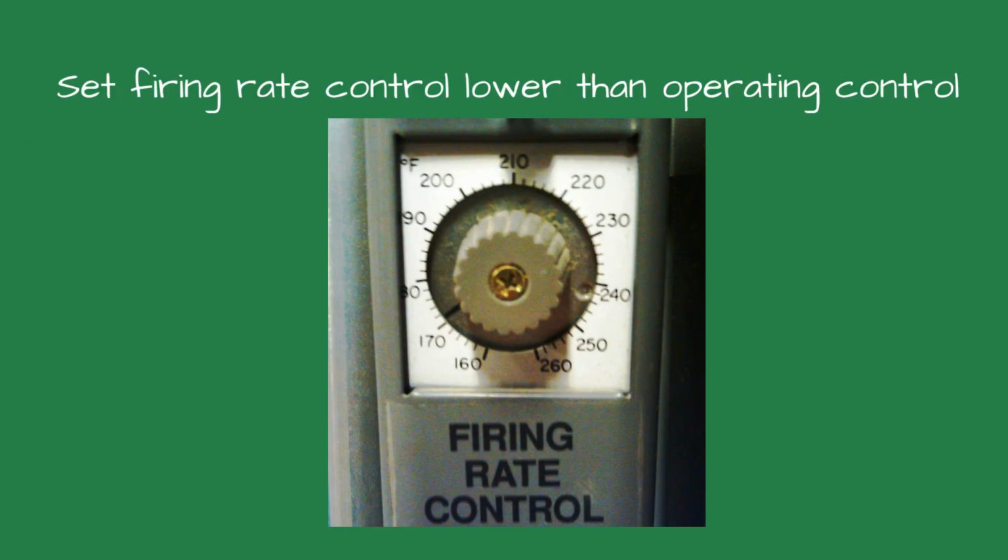The firing rate control is usually set at a lower set point than the operating control and limit control. For example, the firing rate control on a typical hydronic boiler will be set at 175 degrees. The operating control is set at 180 degrees, and the manual reset set around 200 or 210 degrees Fahrenheit.